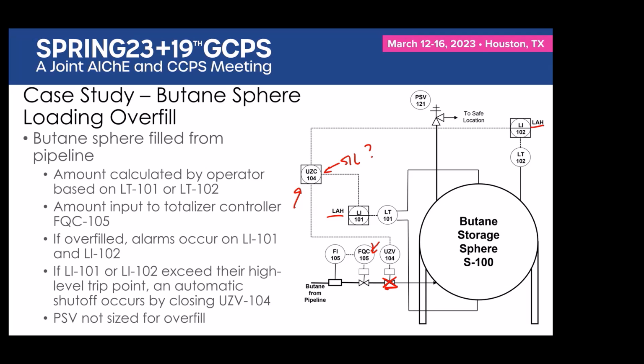So I guess my comment there on the big picture level is that the simplified LOPA has a lot of conservative rules attached to it because you're trying to do a lot of risk analysis quickly with minimal input. But when you shift over into fault tree world, now you've got more flexibility, but that also requires you to do a lot more analysis of what the actual situation is and a lot more research in terms of justifying and getting traceability for the numbers that you're going to put into your fault tree.